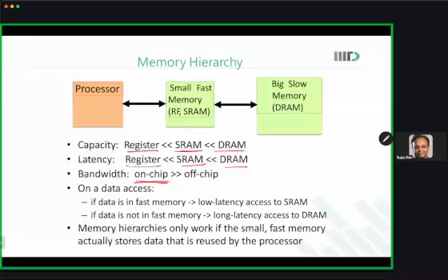The pins have a lot of inductance, capacitance, and that results in huge amount of delay. That's why anything you need to do off chip is, let's say, tens or thousand order of magnitude higher compared to what you can do inside the chip. So your question was why we don't use registers to build memory? Yeah, because that will be hugely expensive.